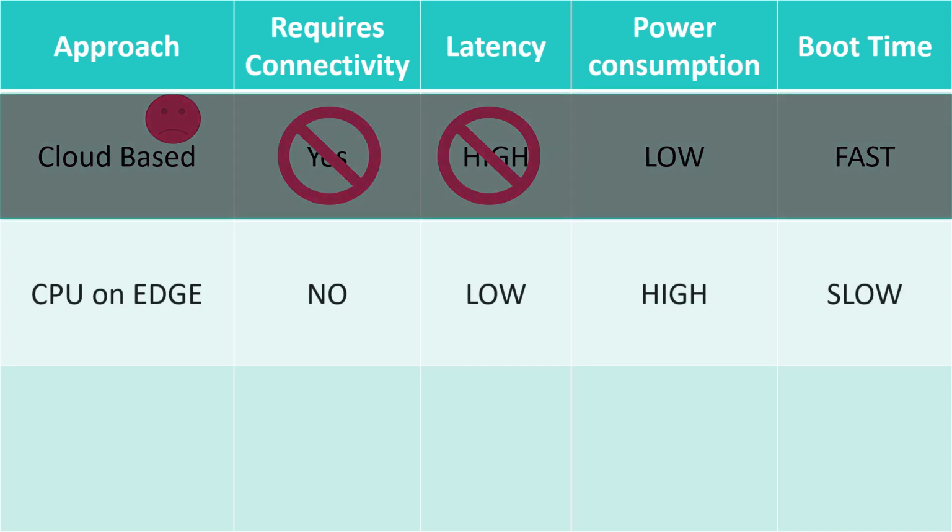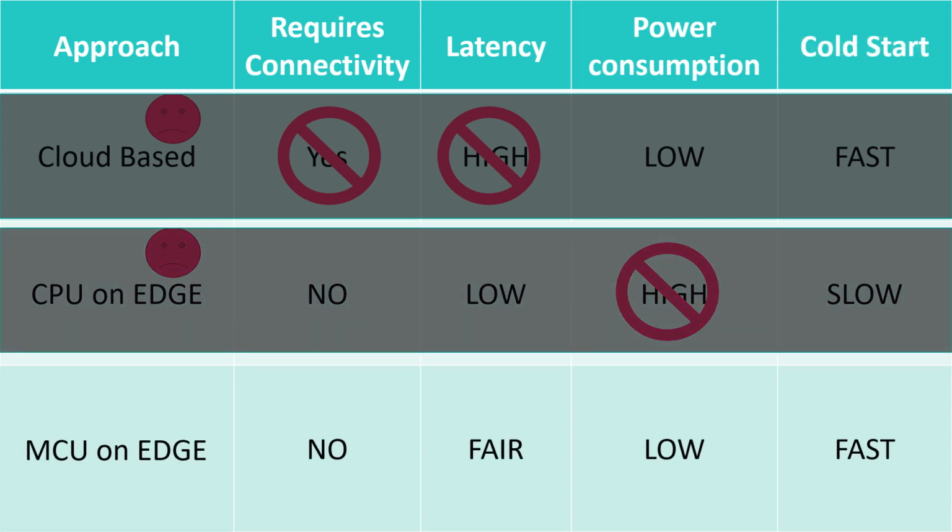On the other hand, when the device must operate without an internet connection, we normally use a CPU or GPU-based device. The edge processor is normally a Linux embedded device. In this case, the price to pay is higher power consumption and longer boot time. But we have in return a very low latency response because of the CPU power that the device has under the hood. The high power consumption of a CPU-based device puts this kind of approach out of the possible solutions for our project. The third approach that we could use is a low power device, such as a microcontroller.